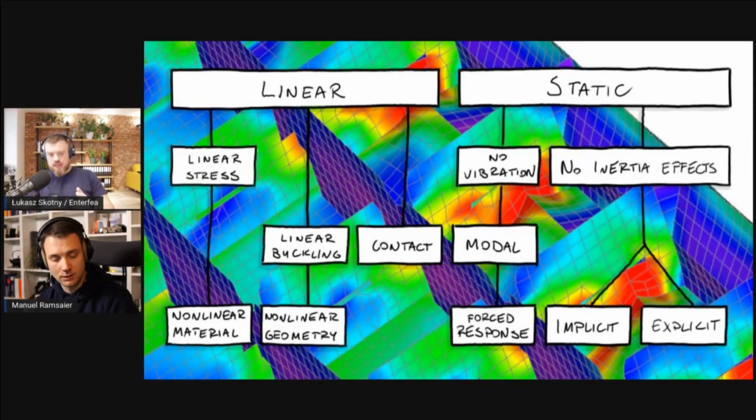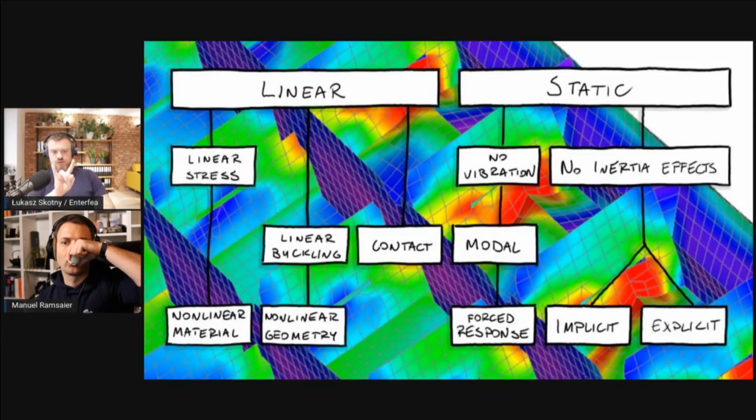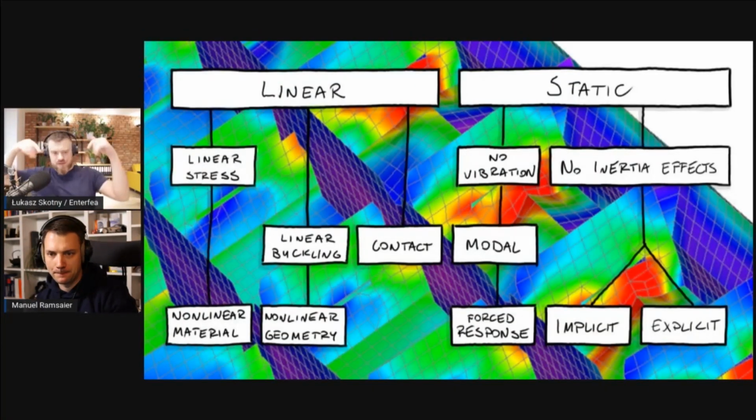The problem with that would be that imperfections kind of have two things. The first one would be if you bend something and compress it, you get a second order bending in the element, and that linear buckling would actually see. But this is not the biggest problem with imperfections.